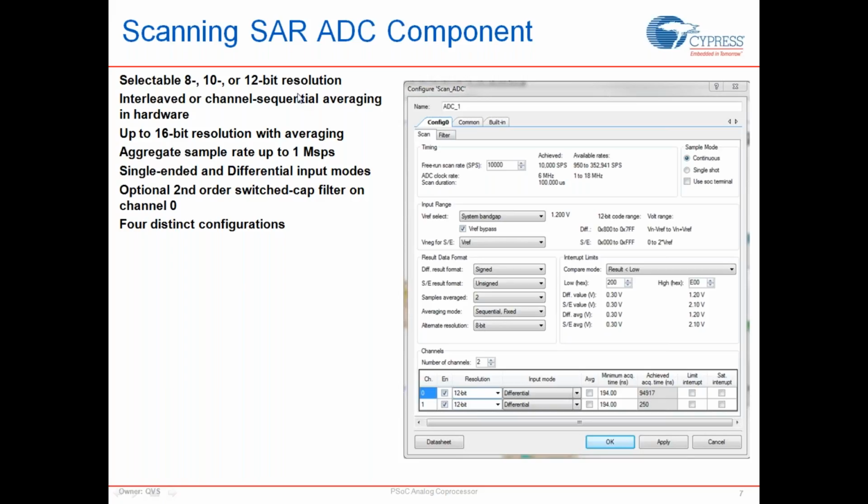So now we can bring in an op-amp output to that terminal, or a reference from the programmable reference block into this reference of the ADC. You can also have an external pin as your reference. It can connect to an external reference chip, as I mentioned earlier.